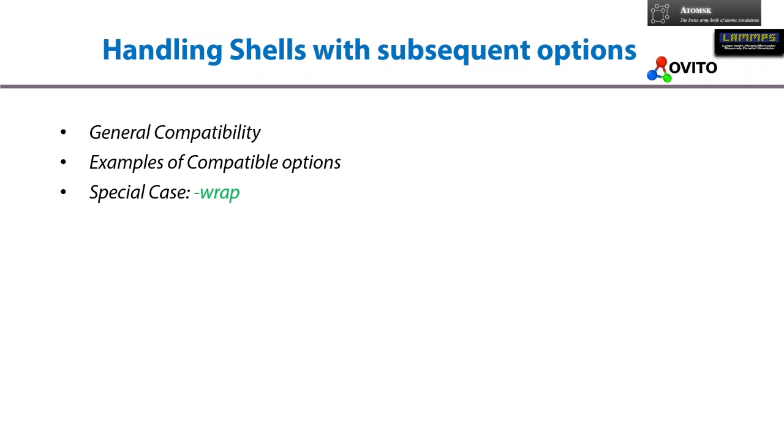In the case of ionic core shell models, if your element goes outside of the simulation box and we apply the option wrap, the whole system does not get back into the simulation box. Rather, wrap only works on the cores. So your cores get drawn back into the simulation box and your shells might still remain outside of the simulation box. It is a special case which you need to keep in mind.